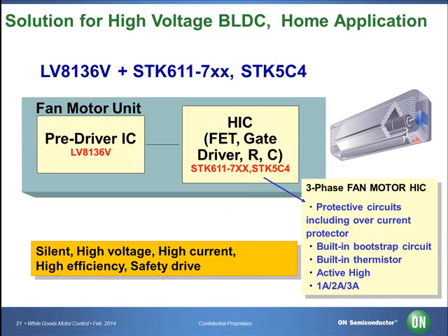In this simplified block diagram solution, we show a combined solution of the LV8136V with an IPM module of the STK611 or STK5C4 series to provide a silent, robust solution with minimal component count. This high level of integration will increase reliability, and the power-saving mode will take the standby current to almost zero.